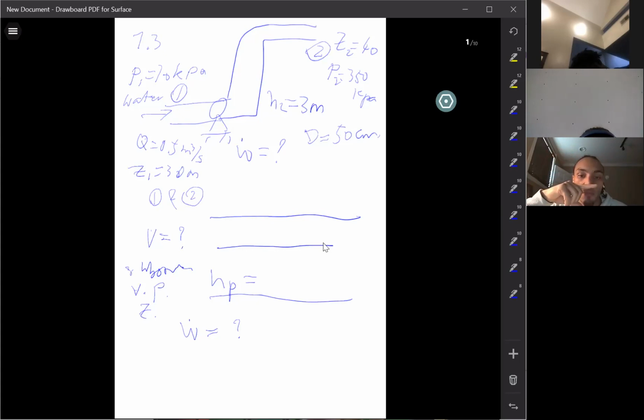What could you do to this problem to make it more difficult, just as an idea? One of the things I can tell the entire class is adding the head loss model. If there are components, you need to find those friction coefficients, K's, then put them together to calculate the head loss. This one, head loss is given, right? So basically it's just a one equation problem.